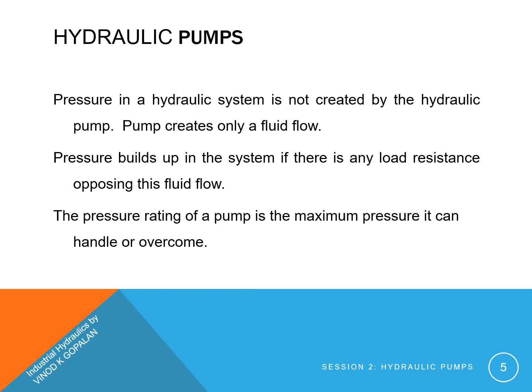Pressure in a hydraulic system is not created by the hydraulic pump. Pump creates only a fluid flow. Pressure builds up in the system if there is any load resistance opposing this fluid flow. The pressure rating of a pump is the maximum pressure it can handle or overcome.